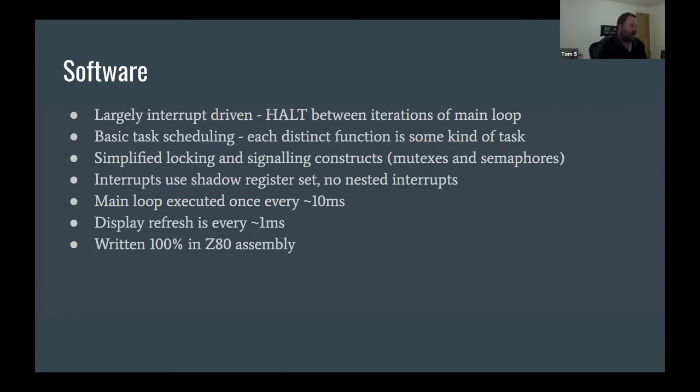I'm using interrupts, and I'm using the shadow register set within interrupts. So I'm not nesting any interrupts, and it's really just a simple way to quickly switch into the ISR and back out of it. I don't have to worry about backing up the registers that are being used in an application or a task. The interrupt can just fire, exchange the register set, go about doing its business, swap them back, and then return from the interrupt.